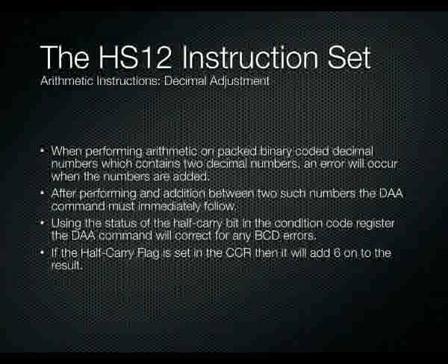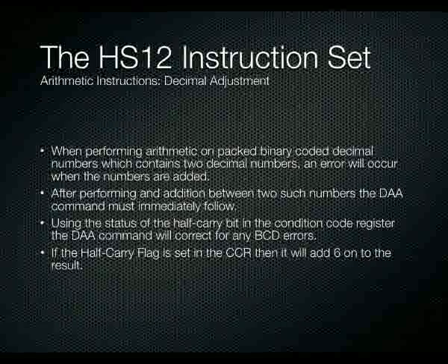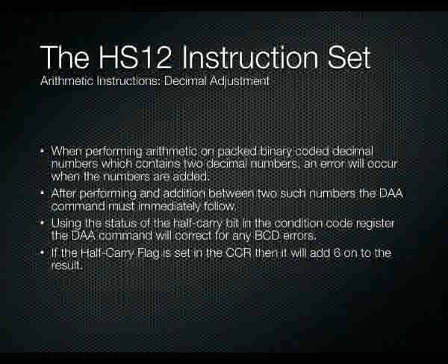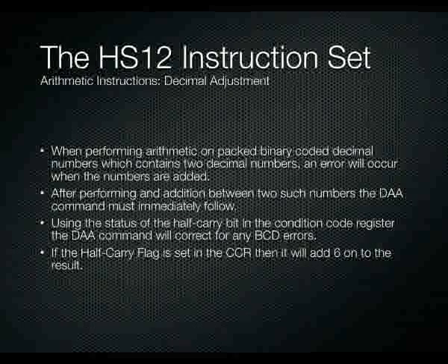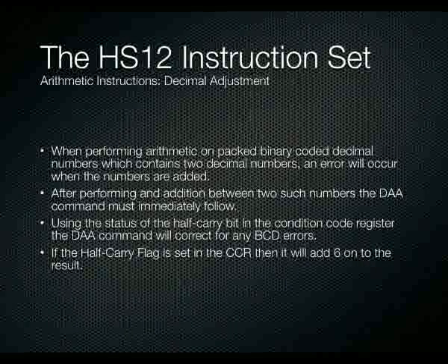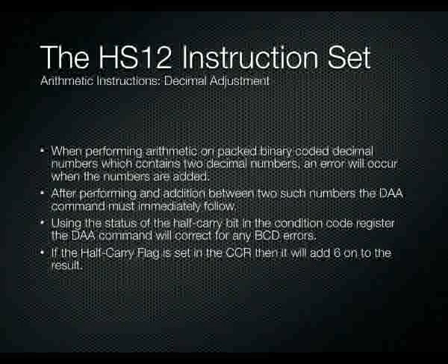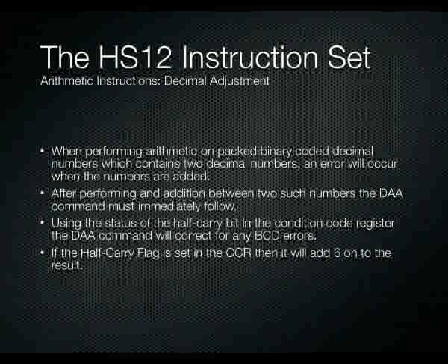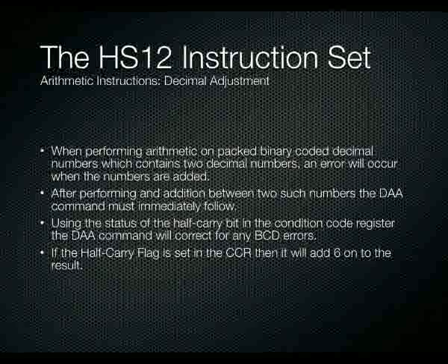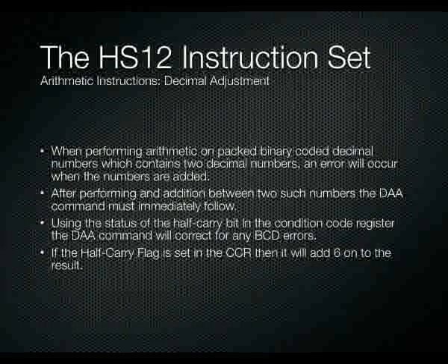Okay, and this works purely on the half carry flag. As I said before, when you run DAA, if the half carry flag is set, it adds 6 to it. If it's not set, then it leaves it well alone, because the number that resulted from that addition didn't in fact exceed 10 in those 4 bits. None of the 4 bits in that number exceeded 10, so it doesn't have to do any addition to correct the numbers.